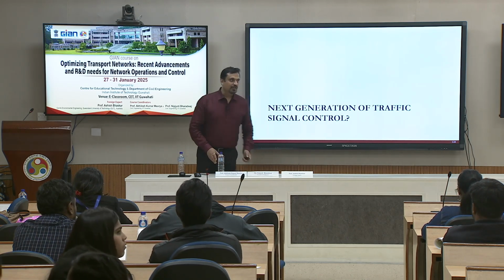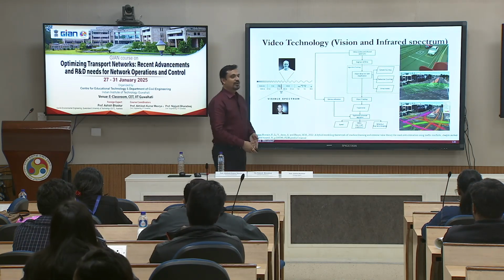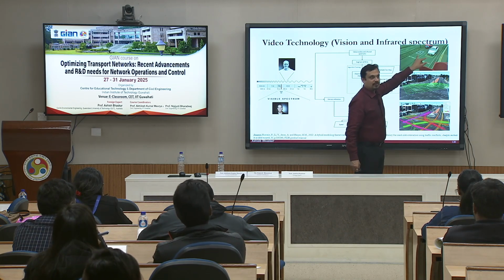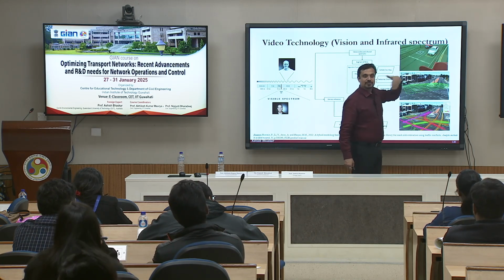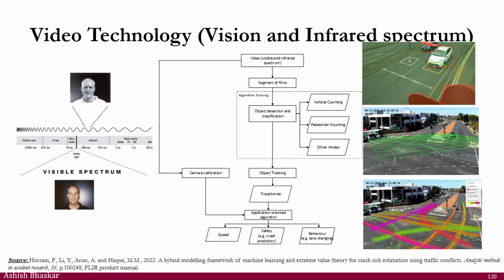So, video camera is what you are saying, okay. Let us go to the video camera image. You are saying that I can have a camera focused on one intersection at one location, make my virtual loops and start counting. Speed is also possible. I can get the speed, but intersection speed will not be of much interest if the camera is at the intersection, since stop line speed is not of interest to me, but that's okay. You get speed, you get counts, you get the vehicle type from there, okay, very good. So, you can get the trajectories, good.